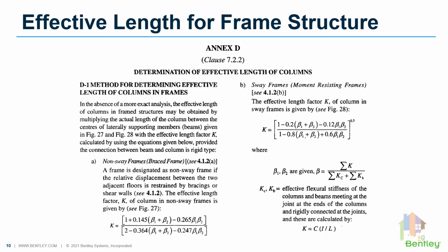For sway or no sway frames, depending on the stiffness of the connecting beams and columns at end nodes, effective length factor is calculated. This is also an approximate method for calculation of effective length, but if you don't consider the deformed shape of members in analysis, then using this equation, effective length can be calculated, which is further used for calculation of Euler buckling stress and compression capacity value.